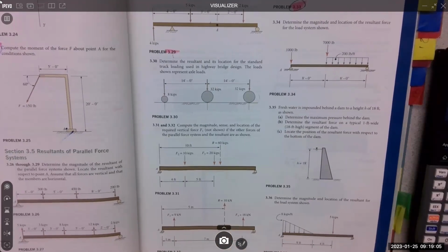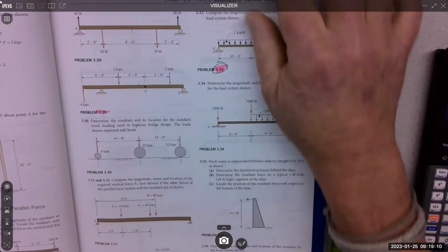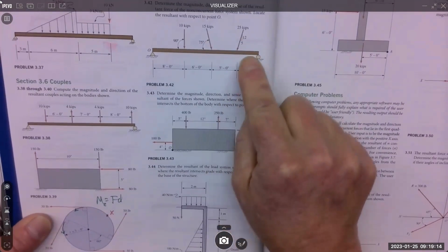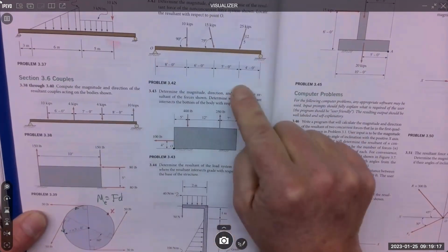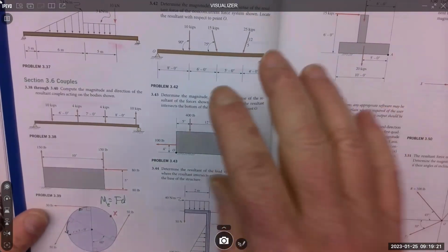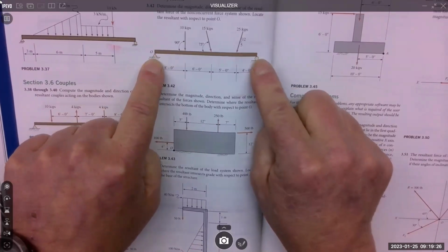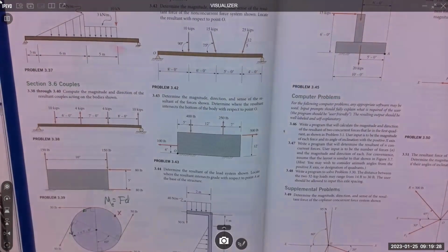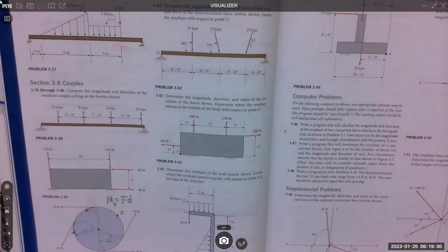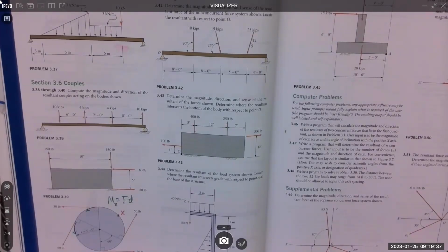But you can see kind of where we're heading, right? We're going to get into distributed loads and try to understand how they work. Then we get into this kind of thing like, oh, there's a bunch of angled forces now and some supports, like what's going on here, right? And the point is we want to be able to calculate what's the load on the pin, what's the load on the roller, because then I can design those. Like, oh, we need a pin that can hold 14 kips. That's a lot of load. That's a big pin. So that's kind of where we're heading.